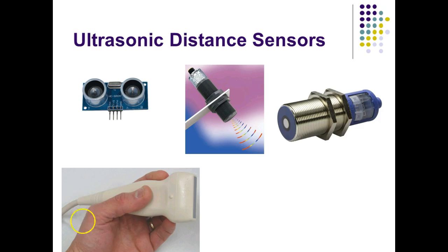And it's becoming popular to put these things all over your car. You see those little circles that split in the center? Those are ultrasonic detectors. One side's the transmitter, one side's the sensor. So now we've got cars that can automatically apply brakes because the ultrasonic sensor is constantly looking at distance. Like I said, my wife's van, when she backs up, if she gets too close to something, it's going to start beeping at her. When she's driving along and a car comes up into the blind spot on her mirrors, it lets her know something's over there.